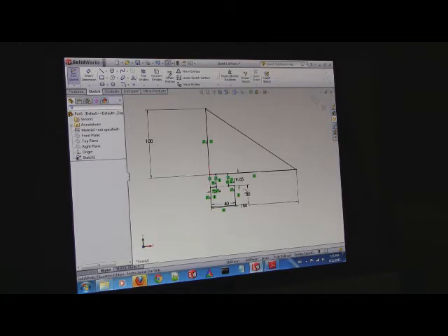This one? But first you have to select the smart dimension. What's up? Somehow, after I did the pairing, it just jumped up. So what you do, it did that because it's unconstrained, because it's blue. Okay. So let's see where we are. You're good. All right. So click that line, hit Control, and that line, and then press collinear. Now you're good.